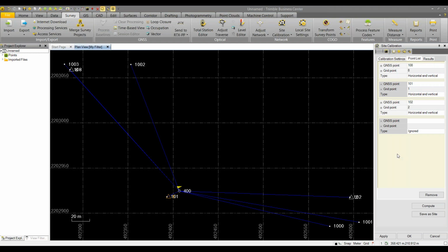And it's important to note, and Adam's touched on this a couple of times too, to know the quality of the coordinates. If you're a one-man or one-woman shop and you do everything, then you'd be a little bit more confident potentially getting away with something like three coordinates instead of 4. However, if you don't know the source of who did the work in the field, or if this has been handed down project over project and you don't have a whole lot of confidence, then you probably want to err on the side of more caution and use more points.